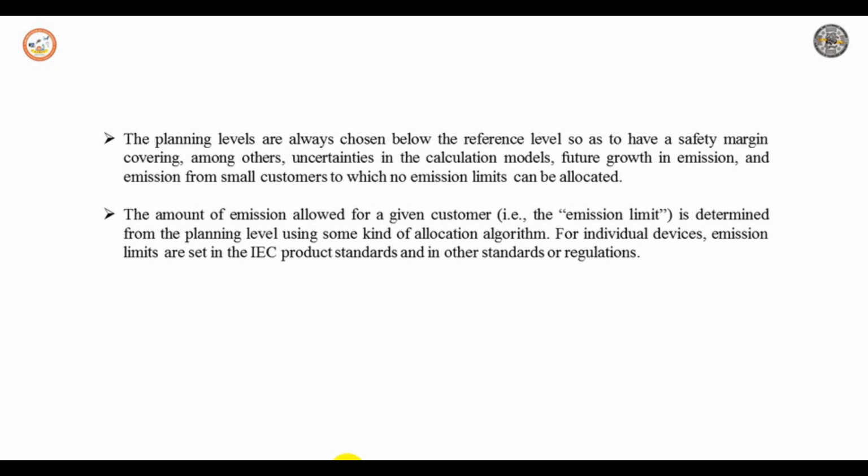even in the existing grid without distributed generation, there is discussion on the choice of reference level. So therefore it is a concern for distributed generation, which remains unknown. One has to be careful to a larger extent as a guiding principle when setting a limit, that is, setting the limit for voltage distortion somewhat below the highest level which is measured at a location where no problem was reported.